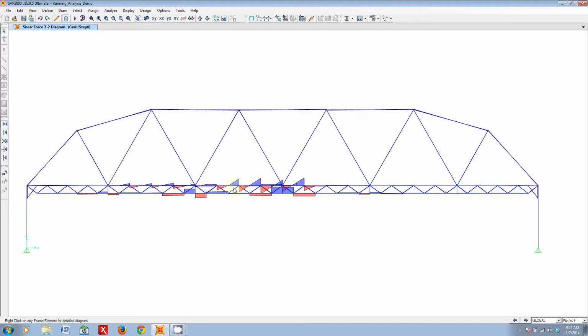So this is basically mostly the shear is local to the members on the decking, and that's where the loads are actually being applied. So that's good, that's what we expect. And then there's pretty much almost no shear happening in the rest of the bridge, which is good because we wouldn't want any shear anyways, because we pretty much assigned frames, releases, partial fixity on these members to ensure that they didn't have transfer.